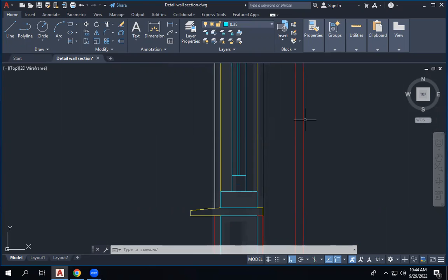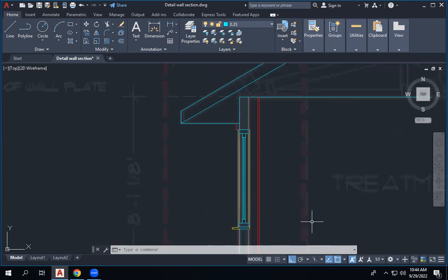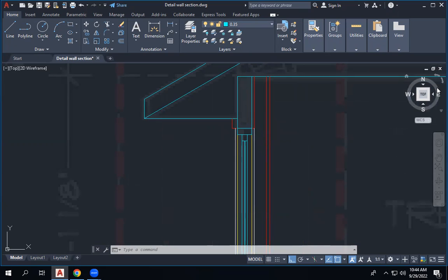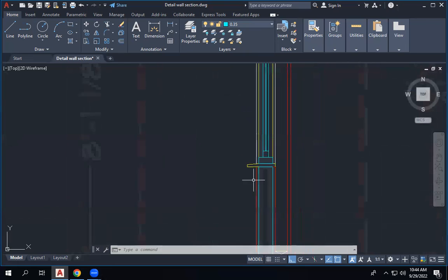When you are giving the dimension for the windows, just give only the height of this one, because all the details will be in the doors and windows sheet and the note. But these things should be marked here. This detail and what you have done here, anything you did to the sill and to the wall and the other things, will be marked here. Only the window part will be in a different sheet. What would you say to the little ledge? Yeah, those things, the dimension and the note, should be marked here. It's not in the doors and window detail. Doors and window details will be only this portion.